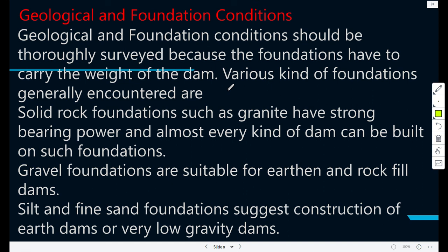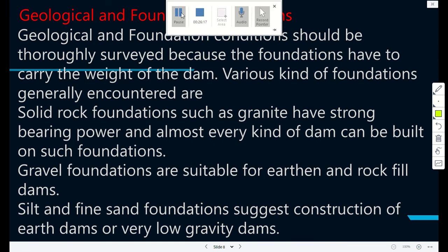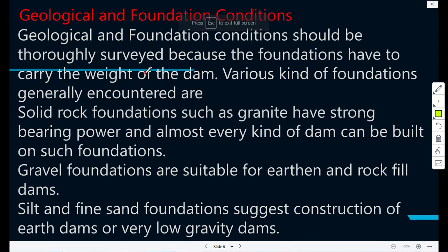So if we find rock, I think this is the best thing we can ever get. Good rock of good strength, not just any rock, and granite, and continuous as well. Because if there are lines of weakness, then that is a potential disaster. So when we are talking about site investigations, you will do a thorough scan of the area and do a test pit.